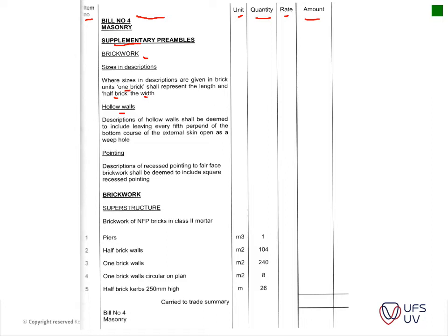What I also usually add here is your binding wire that you have between your hollow skins on both sides. Every fifth layer there should be a reinforcing connection, spaced at 1 meter intervals or so, I can't remember off the top of my head. Then it continues to pointing.